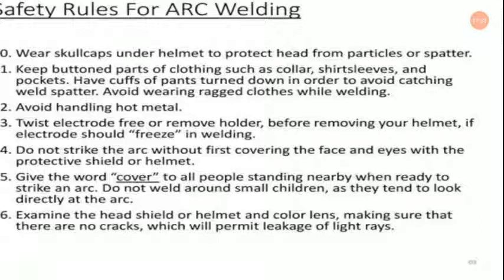And give the word cover to all people standing nearby when ready to strike an arc. That you should maintain. Okay. Do not weld around small children as they tend to look directly at the arc.